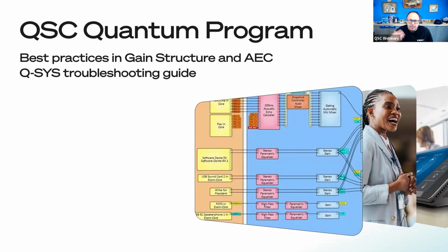It's important to set gain structure as a basis for all audio in the system. And just remember, garbage in is garbage out. If I bring a horrible signal in and I can't process it in the input phases of my design and get whatever bad characteristics there are out of it, then I'm going to end up just transferring those same bad things out. There's no magic fix for having bad audio coming in. Now, there are some things that we can do to manipulate that audio, and we'll get to that.